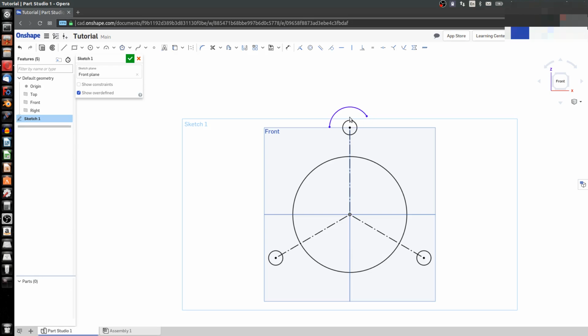I'll go ahead and finish up drawing some dimensions and elements of this sketch. I'll give this a dimension. When working with concentric relations, a dimension can give me a certain wall thickness right here. And so I can say I want a wall thickness of 0.35 inches.